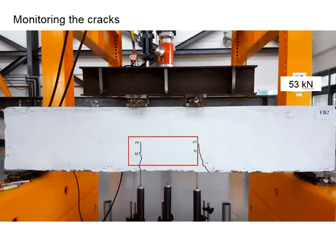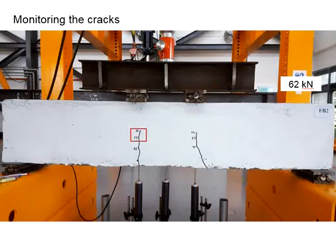If you observe any cracks on the surface of the beam, you can use a marker to mark the locations where the crack ends. Indicate the load level when the crack ends. Once everything is done, you increase the vertical load further, and you observe the further propagation of the cracks.